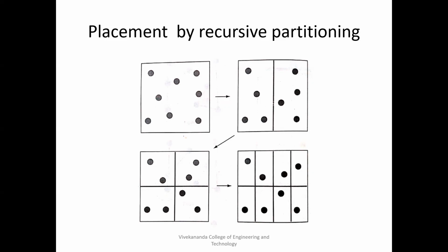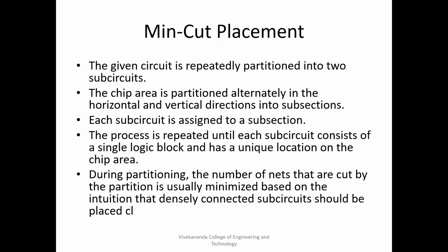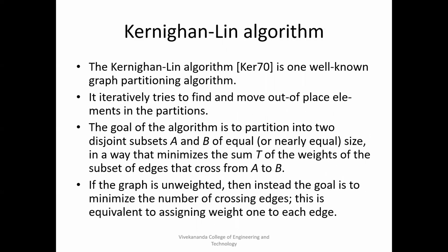If you have to connect a mux and an adder together, you cannot keep them very far apart. They have to be placed one next to another. So you have to design those two blocks such that one becomes a mux, the other becomes an adder. So at every iteration you partition the module or the layer into sub-circuits, and those sub-circuits you design looking at how they have to be connected.